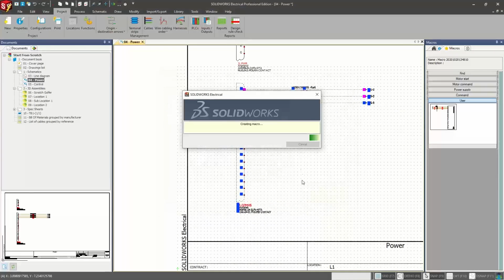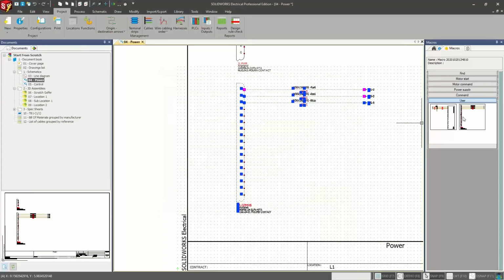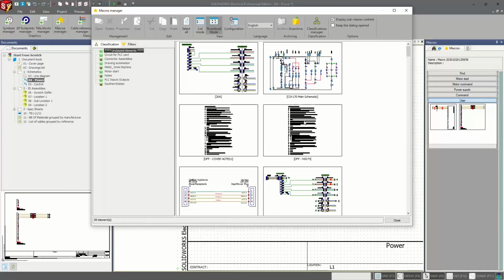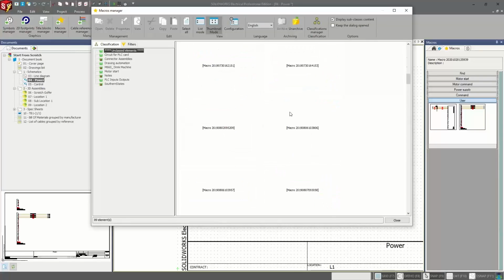I would recommend you keep this one and leave it alone, because that's a finalized schematic, an approved circuit that you're allowed to use. But you do have the ability to copy that in your library and create a new one, or maybe change the manufacturer part, or change the back shell from a straight to a 45 or a 90. You can do that as well.